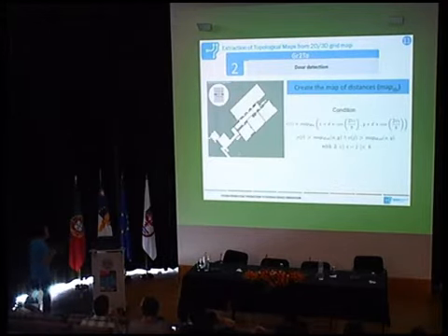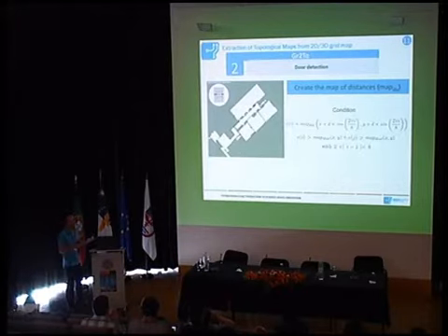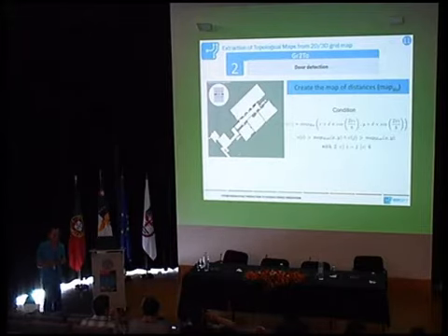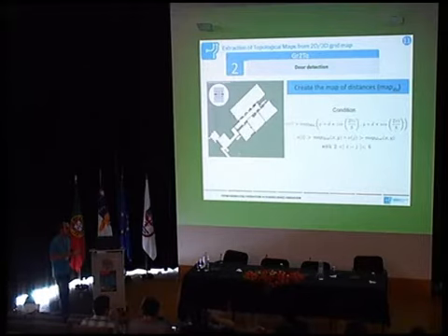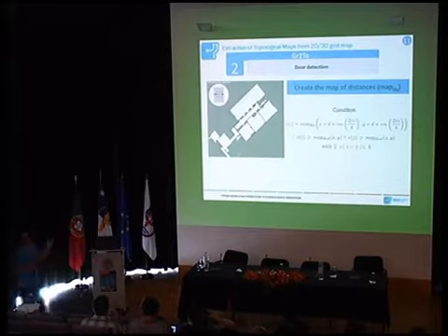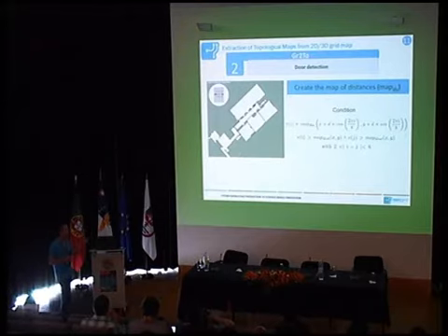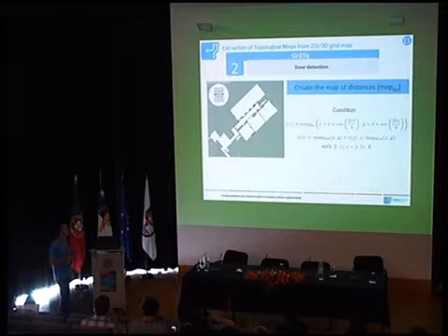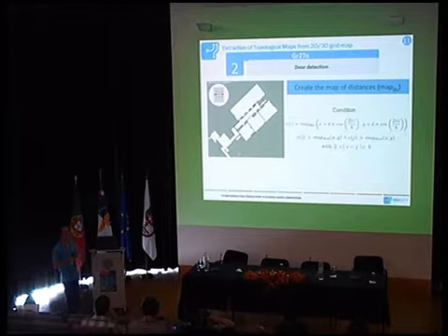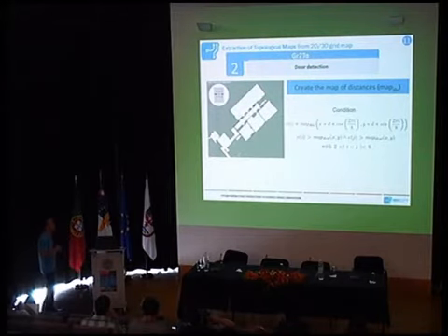Then how do we detect the doors? The concept is very simple. We have predefined the door. We know that the door has a certain length. For example, imagine that the door is predefined to be between 90 centimeters and 100 centimeters. So we first construct the distance map of our topological maps, and where there is a place with a distance to the closest occupied cell inferior to the predefined size of the door, that can be a door.